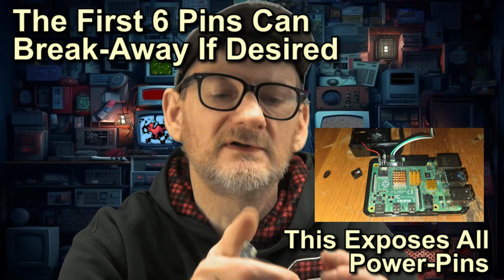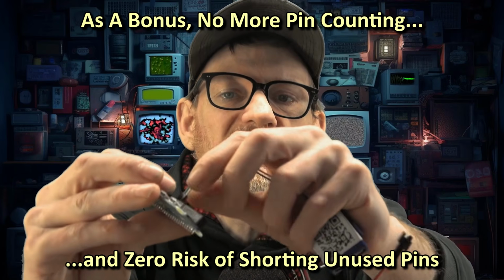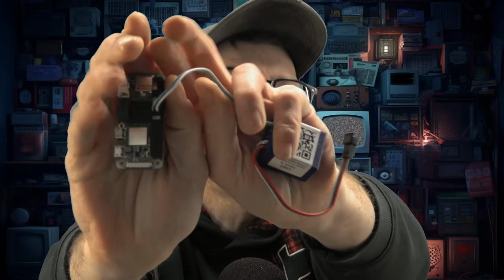So, for example, of course, on the level shifter, you've got a choice. You can either use the traditional GPIO 18. So you take your green and your white, and you locate the green and white dot, and you plug that in. Nice and secure, as opposed to the old method of having 2 separate individual wires just hanging on the bare pins. If you want to use the SPI method, well, I've exposed those 2 pins as well. And just make sure the green and the green are lined up and the white and the white. And you've got a ground and the SPI MOSI output. And there you go. Just a simple little bonus I'm throwing in as part of the level shifter kit.